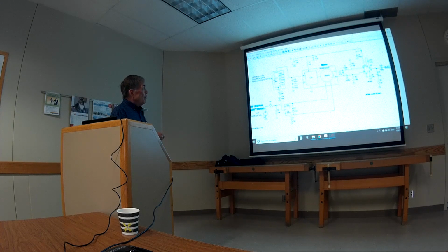And then I have two more components down here on the bottom. This inductor and capacitor. You wouldn't actually put them both together in series, you do one or the other. But once again, it's a matter of pulling that crystal a little bit. We wanted to tune it a little bit, so we could do it with an inductor or a capacitor down here, not probably both of them. But this is just for illustration.